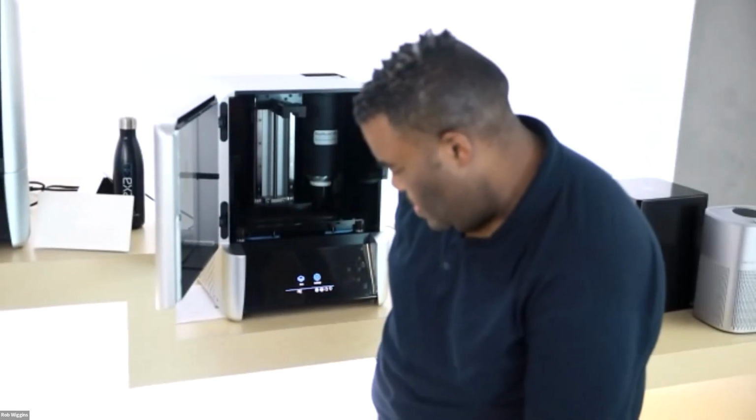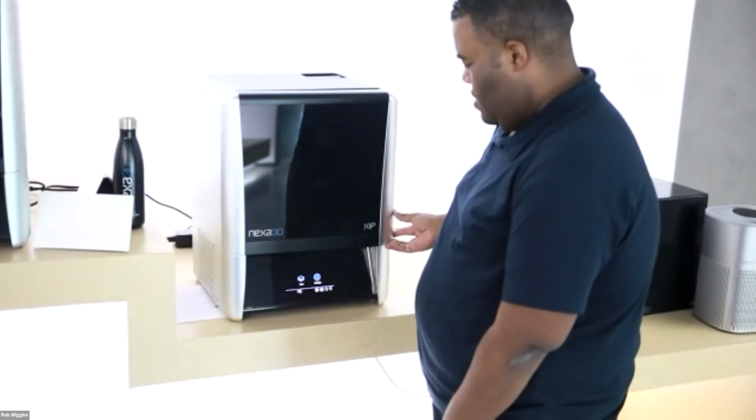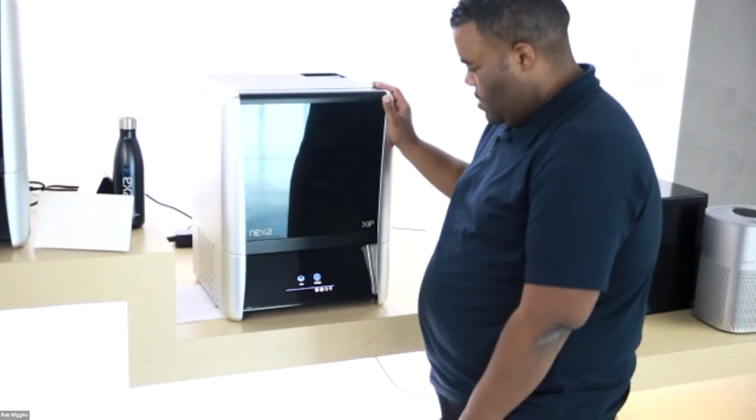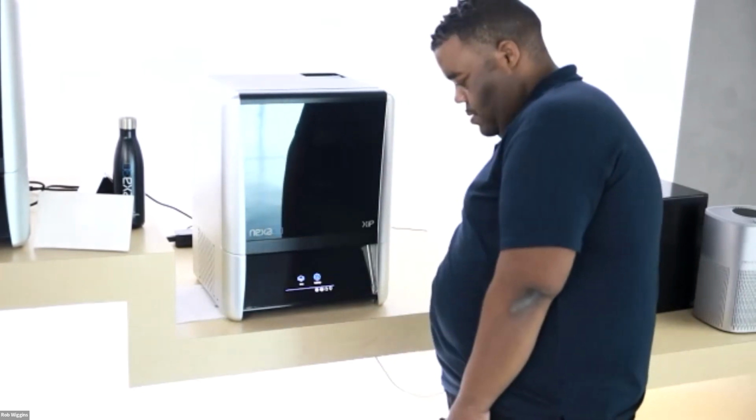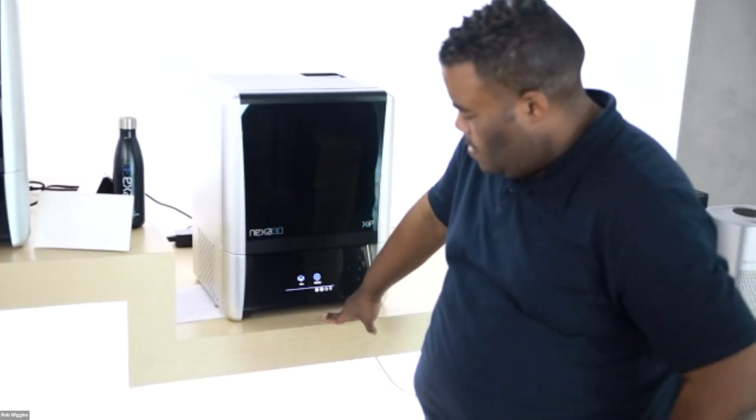There you go. And just to add to that, XABS, obviously ABS is one of the most popular consumer product materials, used in injection molding and all of that. We've got XPeak, which is a PEEK analog. It can get up to like 230 degrees Celsius under pressure, that's a heat deflection temp. So it's really useful for tooling applications where you're actually printing the molds out and doing tooling with those molds. We've got a PP analog, XP polypropylene, and a whole bunch of different high-speed modeling materials.